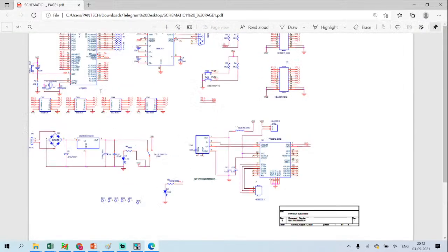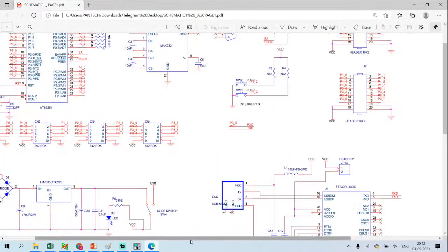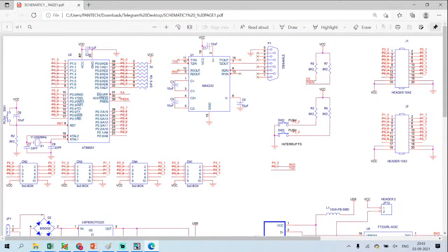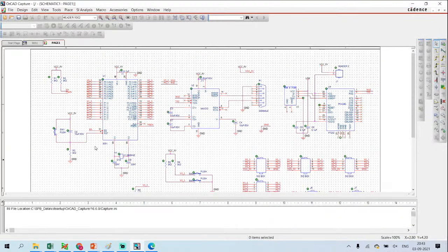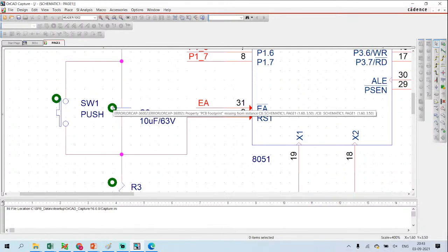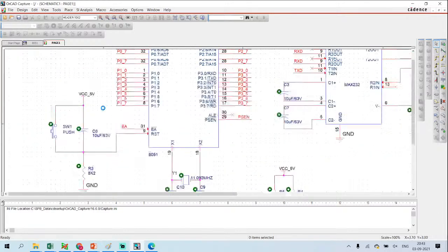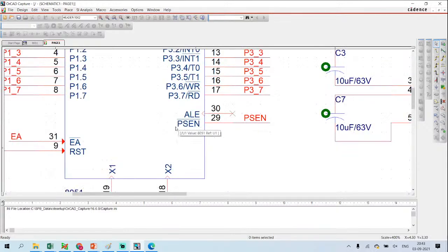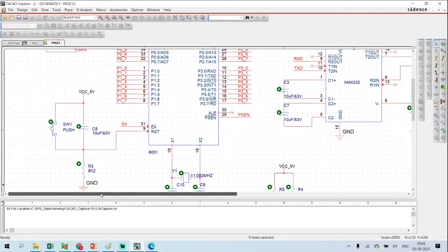Okay, so this spot, we have the reset pot here and the crystal pot here. Let us verify the reset pot. The reset pot is here. These green colored dots are for errors. Just before this, I ran the DRC and checked. We have not linked the footprints, so it's showing an error. I will tell you how to remove this error.